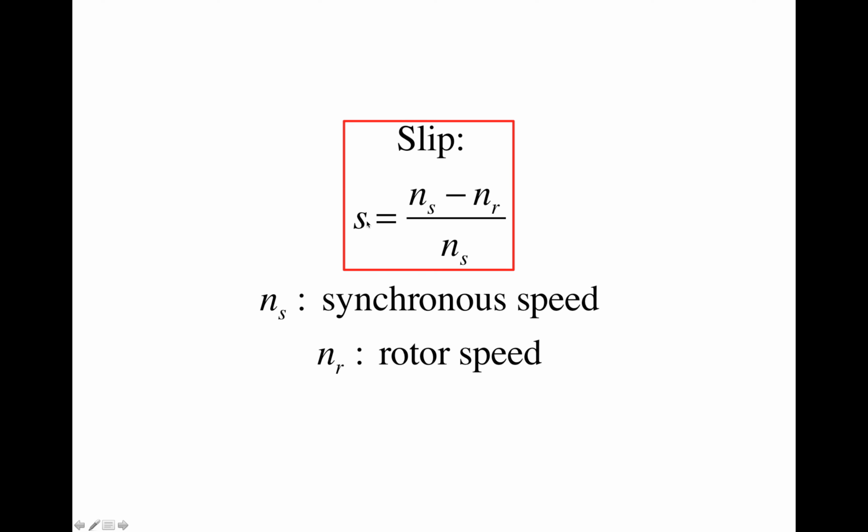And on the other extreme, when the rotor is locked, when the rotor is not rotating at all, at a stationary position, Nr equals zero, which is at the beginning of the acceleration process, at the starting point. Either when you hold the rotor to a stationary position, or when you open all the end rings so there's no induced current.